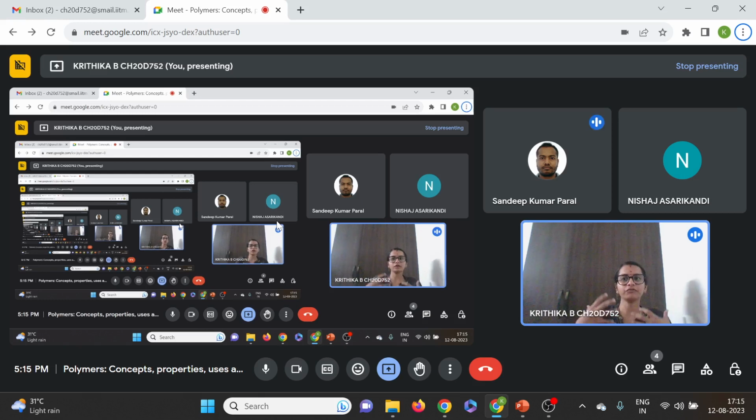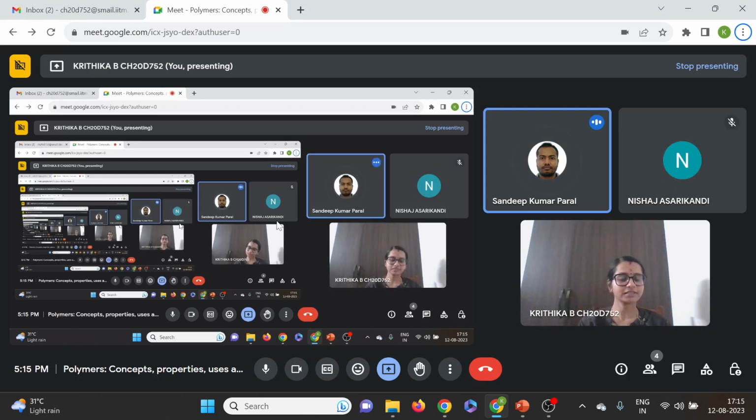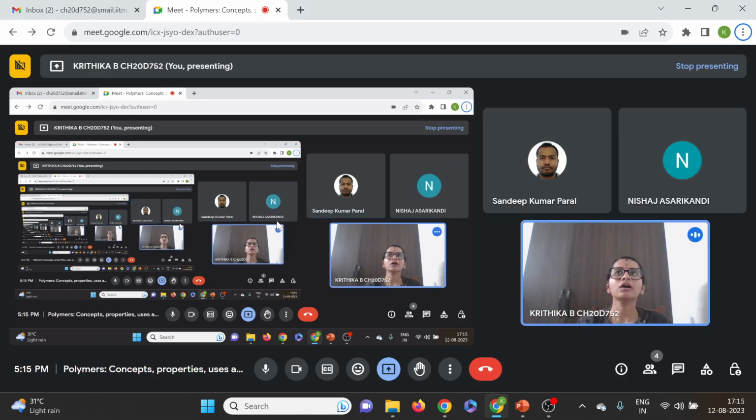So you mean that we first need to go to FTIR to know the chemical composition? Yes. Then for thermal, DSC will help you. Always, in understanding an unknown polymer or working on a new material, you cannot just stick to one analysis technique. You will be doing multiple techniques, and from the combination of those you will get to know what the actual polymer is.